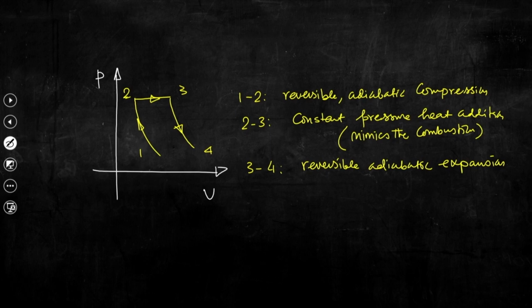So, we did not connect the state point 4 and 1, though the condition of the working fluid at state point 1 is the ambient air, and when the working fluid comes out from the turbine, it is discharged into the ambience. So, the state point would be ambient condition. Now, temperature will certainly be higher than the ambient air, but we are directly discharging into the ambience. So, this is the open cycle.